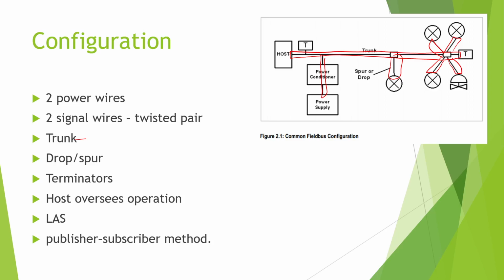We do have a communication rate of roughly 31.25 kilobits per second. We got a pretty quick, all right? That would be, what, 31,250 basically bits per second. So that's faster than most of the serial that we've talked about so far. Your response times will be anywhere between 32 microseconds. Let me write that one out. 32 microseconds and 2.2 milliseconds. All right. Now, how do we go from micro to milli? Anyone remember?